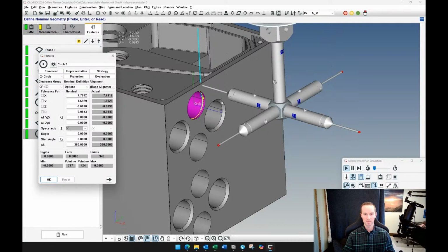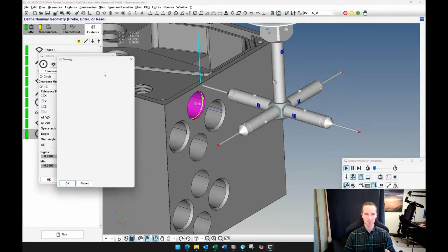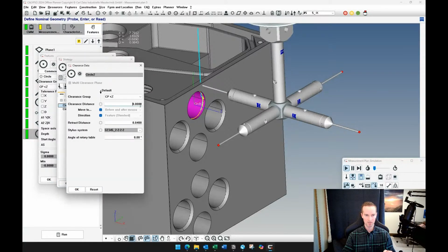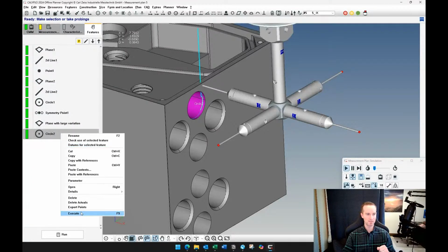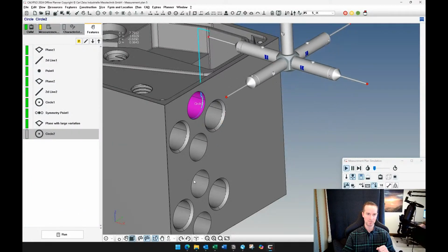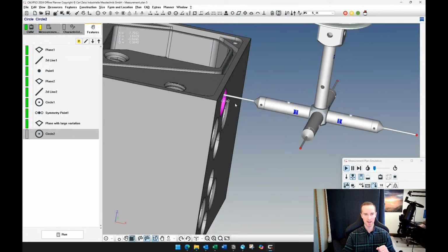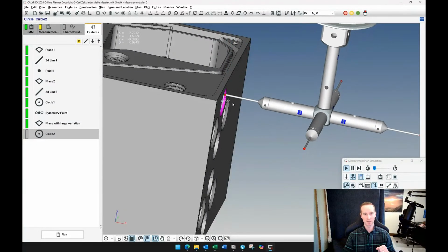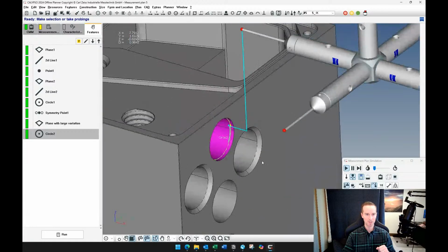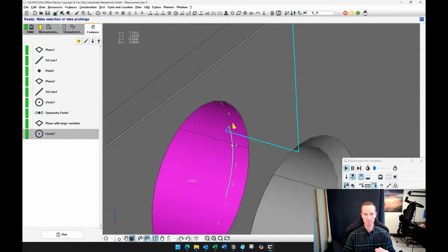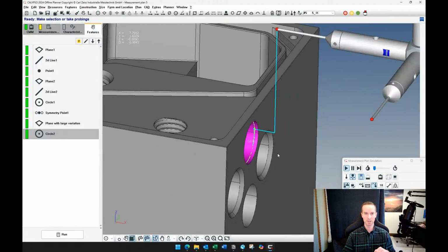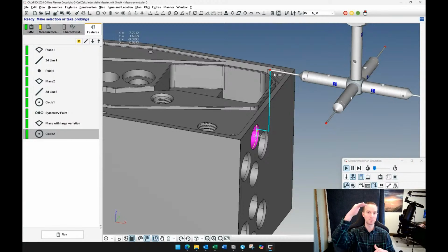So in this scenario, what we need to do is use a clearance that is coming out of the surface. So this is a 1/2 inch from that scan path. And we're going to execute that again. So you'll notice it comes and it clears that cylinder before it dives in and does a retract distance. So here we have that this is our 1 millimeter retract. This is our 1/2 inch clearance distance. And there we have our move to the clearance plane.